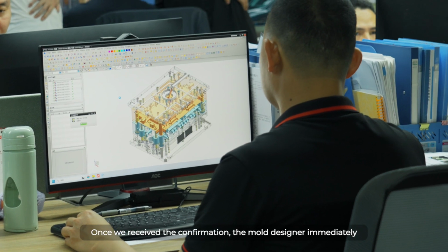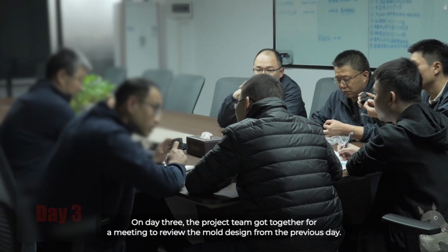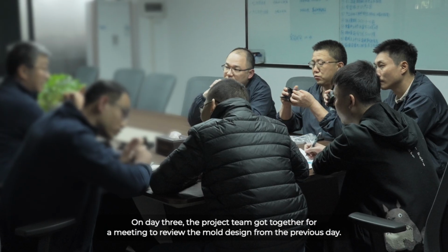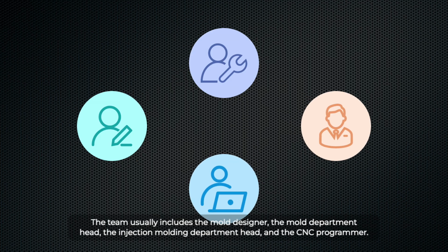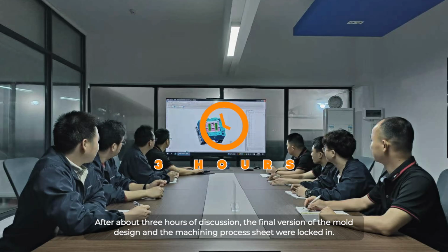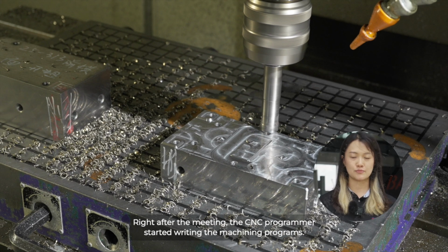Once we received the confirmation, the mold designer immediately started on the mold design, planning to finish the drawings within a day. On day 3, the project team got together for a meeting to review the mold design from the previous day. The team usually includes the mold designer, the mold department head, the injection molding department head, and the CNC programmer. After about 3 hours of discussion, the final version of the mold design and the machining process sheet were locked in. Right after the meeting, the CNC programmer started writing the machining programs.